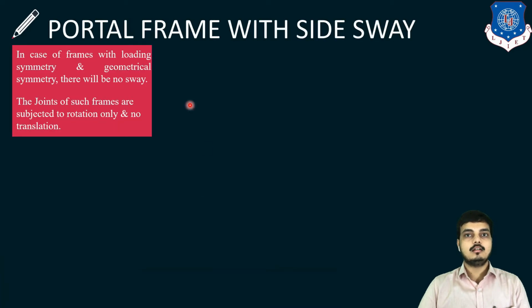So now let's move towards the concept of the portal frame with side sway. It says that in the case of a frame with loading symmetry and geometrical symmetry, there will be no sway.